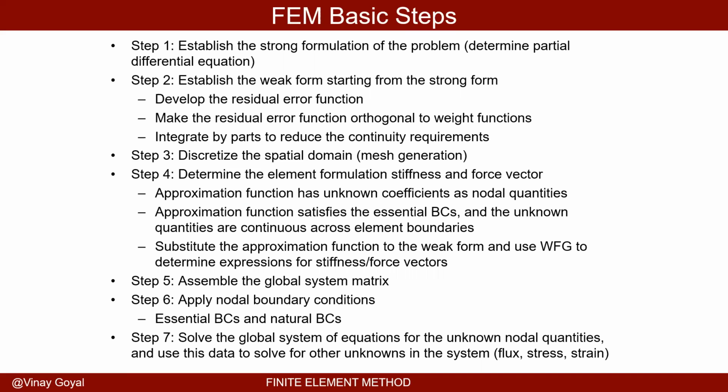So I have the strong form of the problem, which is really the partial differential equation. And what I want to do is develop the weak form from the strong form. We found that by using the weak form, we can reduce the continuity requirements, and that allows us to approximate the solution to the partial differential equation by ensuring that we can minimize the residual error and making it orthogonal to the weight functions. And we can then integrate that over the domain, and we can then reduce the error in the average sense.